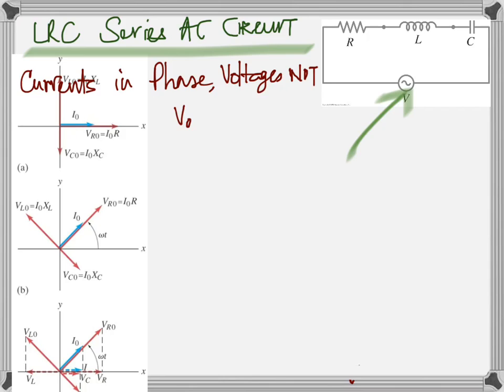And in physics, rotation in the counterclockwise direction means leading. So the vector which showed you current was along the positive x-axis. The current through the inductance is also along the positive x-axis. And because it leads, you rotate it counterclockwise by 90 degrees. So the voltage is shown along the positive y-axis, right? Got it? That's why you see it along the y-axis. Now my life is easier, I hope.